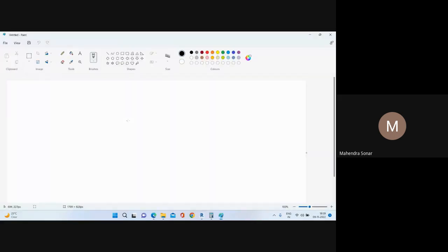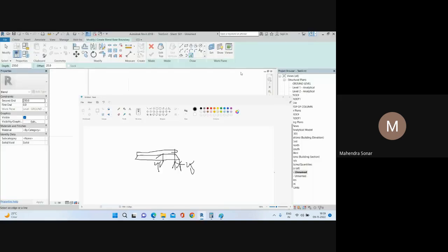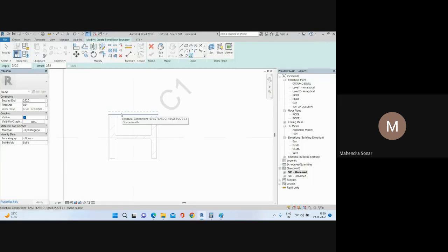Right, so this is my grout like that, and this is my base plate. So if I give this thickness of this grout 25 mm, so this distance it should be 25 mm. Okay, so I have given the offset from the edge of the base plate. So edge of the base plate where this one. So I will just use the offset and just add here base plate.